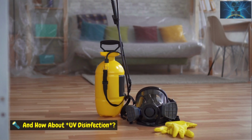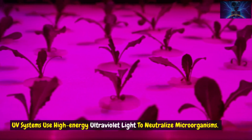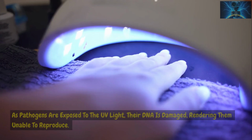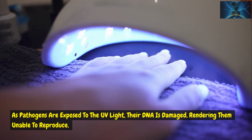And how about UV disinfection? UV systems use high-energy ultraviolet light to neutralize microorganisms. Water passes through a chamber with UV lamps. As pathogens are exposed to the UV light, their DNA is damaged, rendering them unable to reproduce.